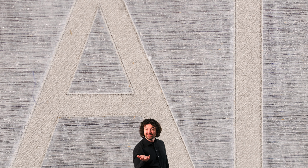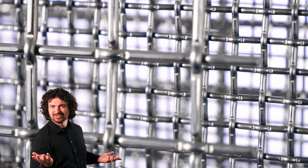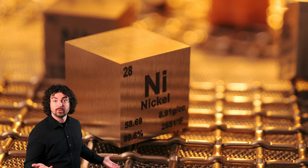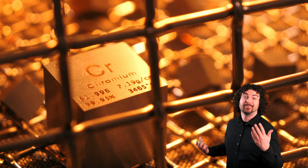Stainless steel has them all beat, except technically aluminum. Aluminum is pretty cheap actually, but aluminum is just not going to cut it in most woven wire mesh applications. Stainless steel is more corrosion resistant, heat resistant, it's way stronger, just to name a few. At the end of the day, stainless steel is one of the most well-rounded alloys out there that is also incredibly common, incredibly cheap, compared to most alloys or elements that you could use for woven wire mesh applications.